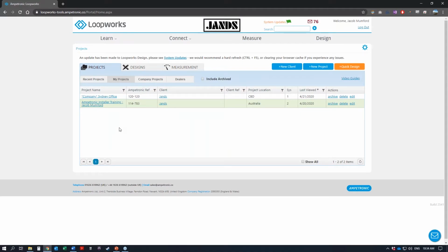Talking about network drivers, the only drivers that have a network capability are the digital drivers. So basically, I would say one of the most important points that they have is you can get some fault monitoring. So if something goes wrong, you can set it up to email you, say temperature reaches max, or the driver boots on and realizes that there's no loop cable connected to it, which could essentially mean, hey, someone's cut the cable. It'll send alerts to you like that.